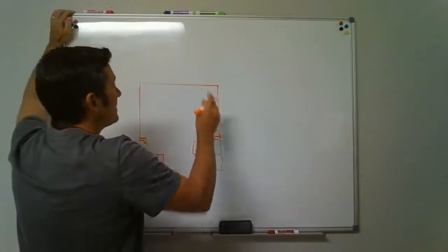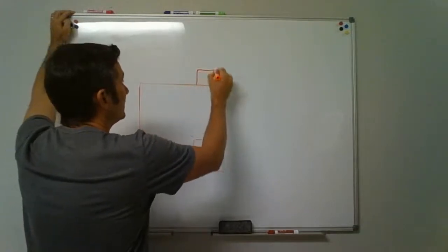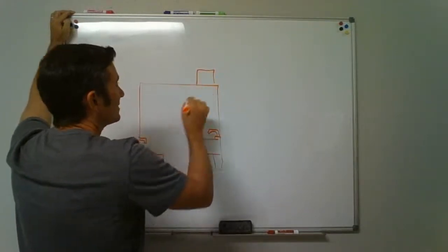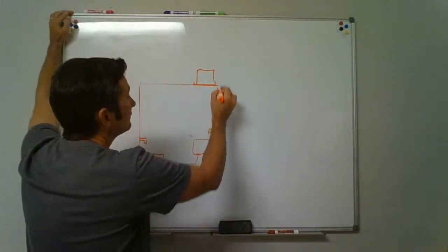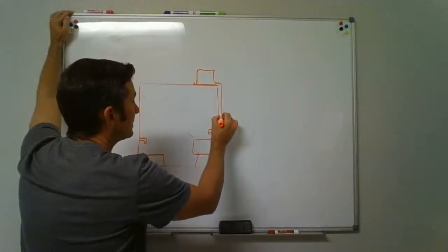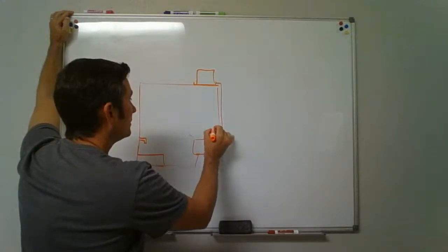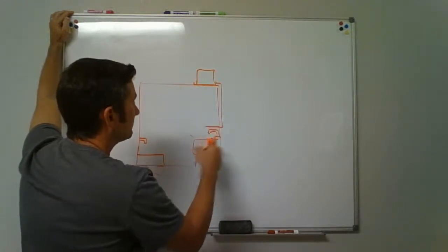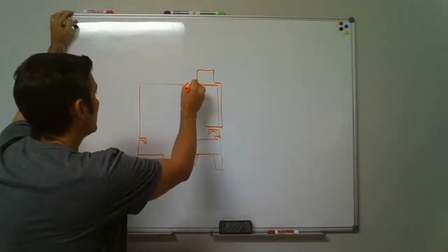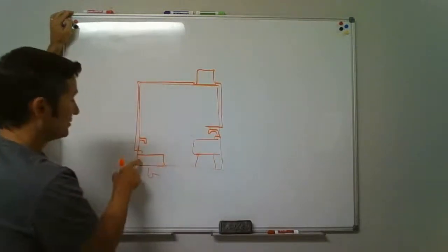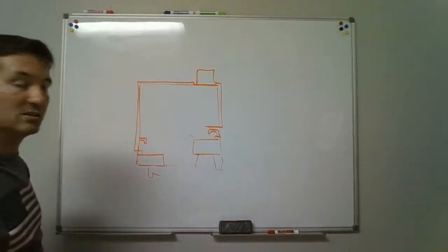And then if there was some framing, or they could suspend it also and support this thing, there could be a little water heater if they've got access. They just got to have access up to it. What we could do is put a pan underneath that thing and pipe it down. This pan could come down and pop out the wall. Now you wouldn't want it right over your faucet probably, but you could do it over to this side, or you could pipe it over and down and let it discharge into the mop sink. It could discharge into one of these sinks if you wanted.